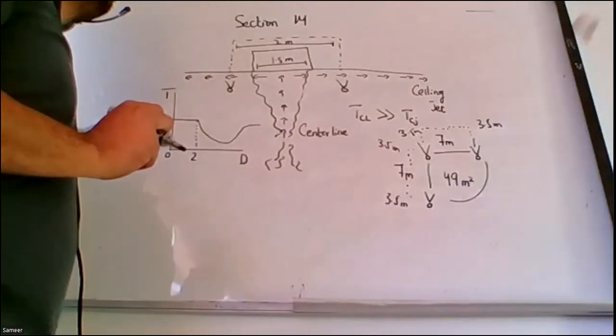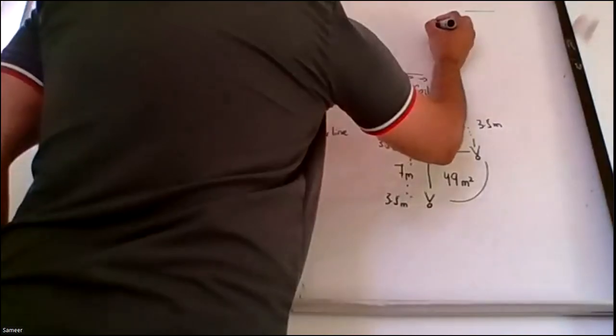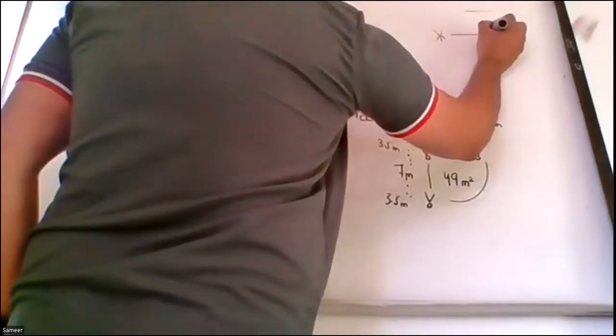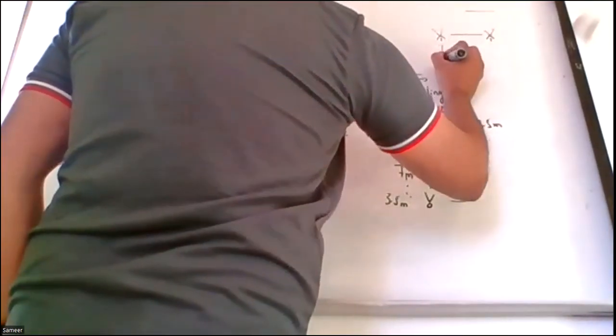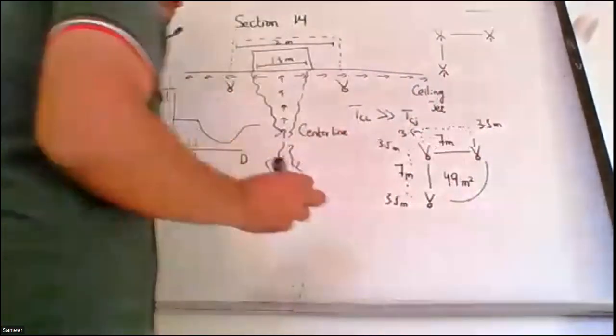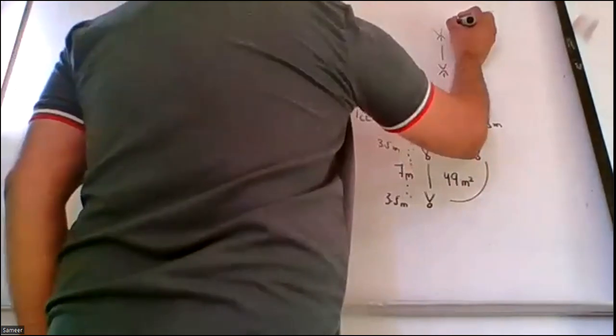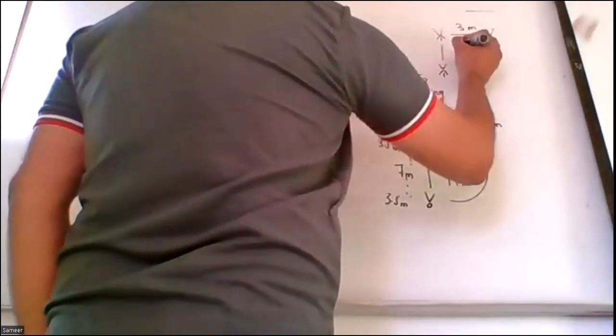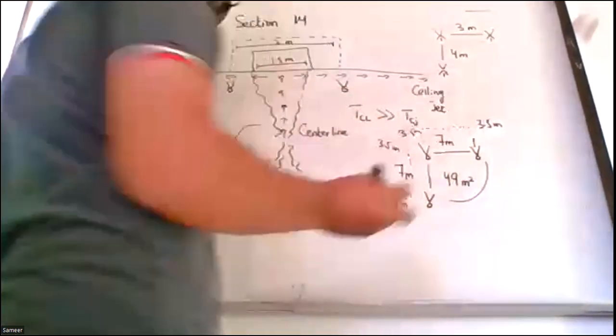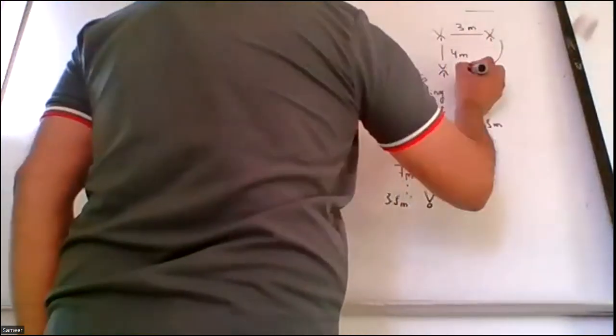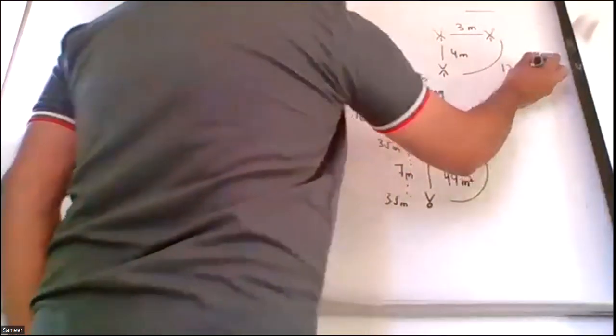Similarly, if we refer to sprinkler systems, NFPA 13, residential buildings, what does it indicate? Branch to branch, the distance should be approximately 3 meters, and within the branch 4 meters. Area of protection, let's say approximately 12 square meters.